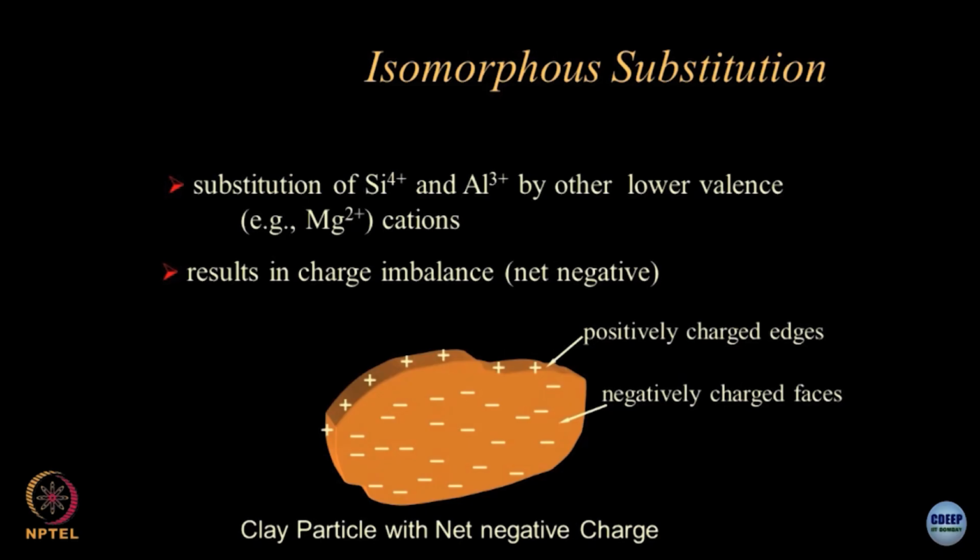So, the fundamental property or the fundamental charge is negative charge and it gets spread on the surface. On the edges you have positive charge. Where will bacteria come and sit on this clay platelet? Quick, where will bacteria come and form a bond? Mostly bacteria is negatively charged, alright. So, the chances are that they will be holding the clay platelets from the edges.